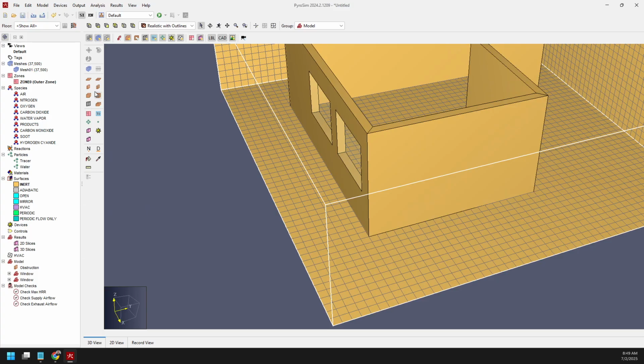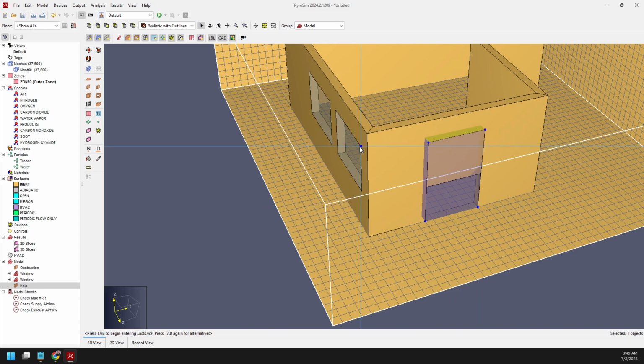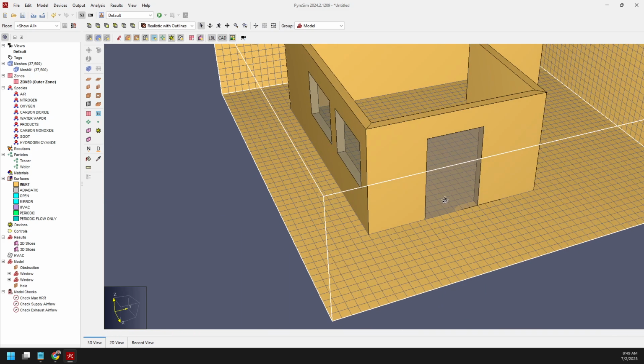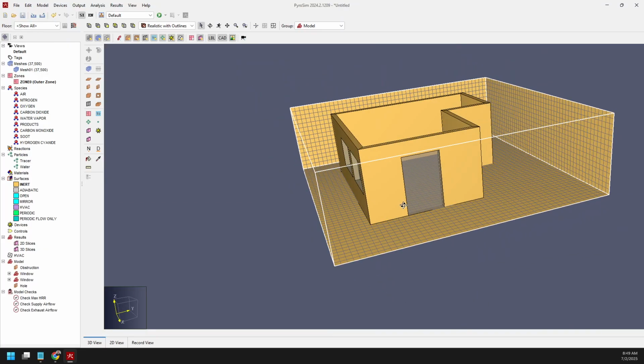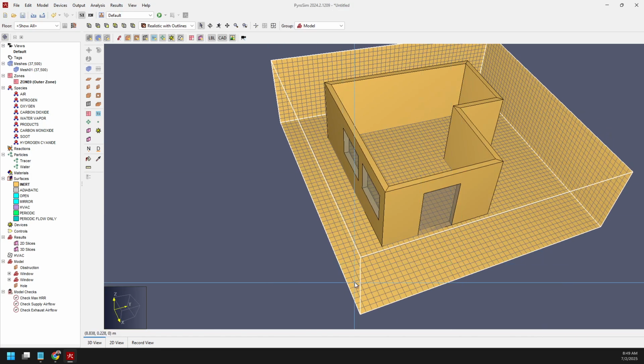Same deal here. I'll start with drawing my door hole. So just go across the width of the door, finish that, bring it up the height of the door that I want, and then add an obstruction or not, into that the same way we did with the window. Although this could maybe be a solid wood looking surface or something instead. So that's that.